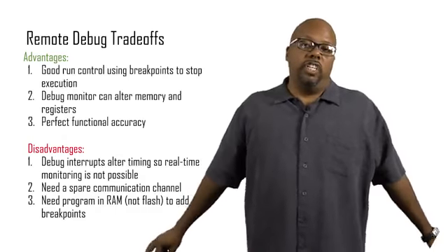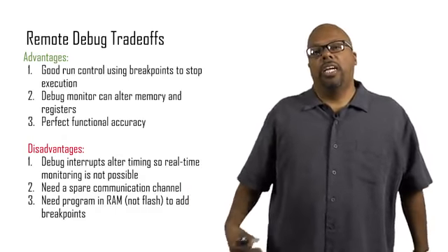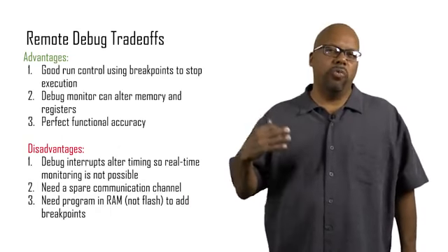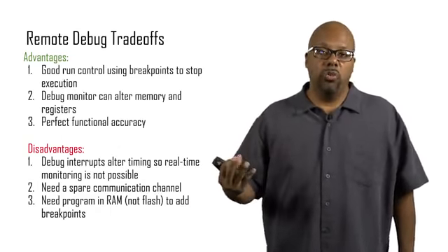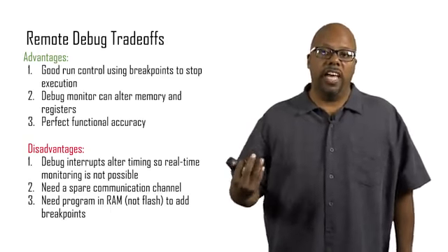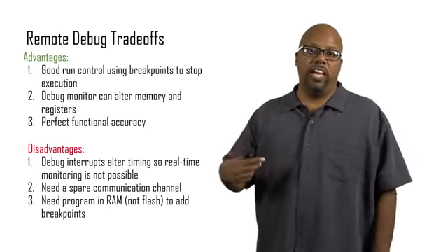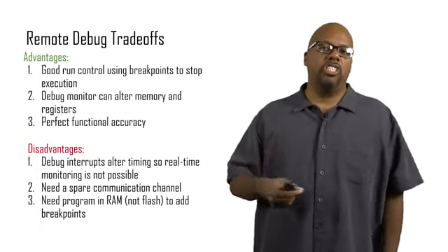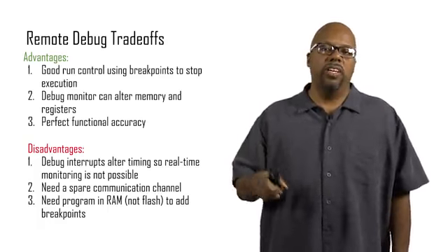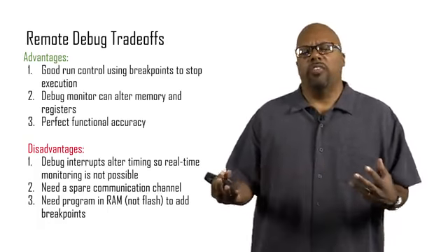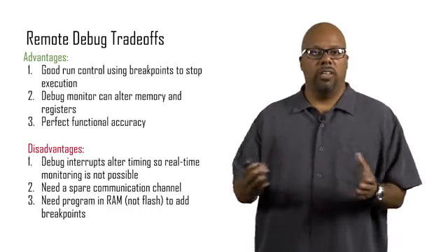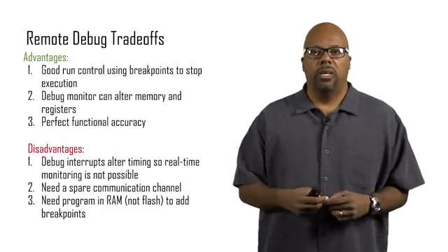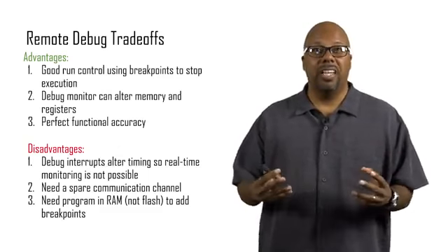Another thing is that you would like to have the program in RAM in order to add the breakpoints. This has to do with how software breakpoints are added. In an Arduino, the program is generally resident in flash and executed out of the flash memory. But you would like to have it in RAM because flash is slow to reprogram and RAM is fast. You can reprogram flash, but it takes a relatively long time. When I say long time, I mean milliseconds, lots of milliseconds.